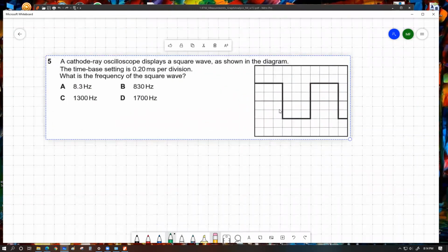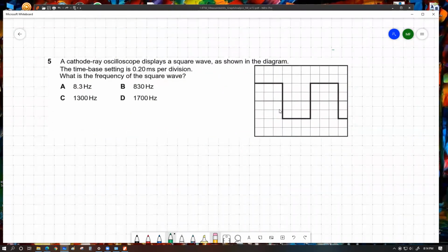if we start to count our wave from here, let's say here is t equals 0, exactly right over here we should have t equals 1 time period. This much should give you one full time cycle, because if I copy this shape of the wave one after another, I should be able to get the full cycle. So I'm taking this much as the full time period, because this point and this point in terms of the wave are similar for one full cycle. So you just count how many divisions are in one full cycle.